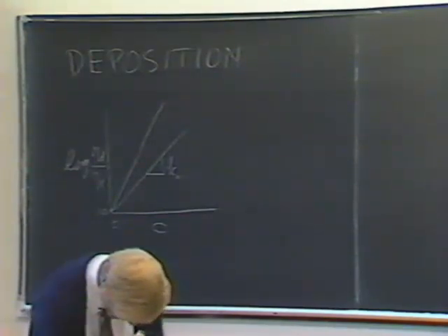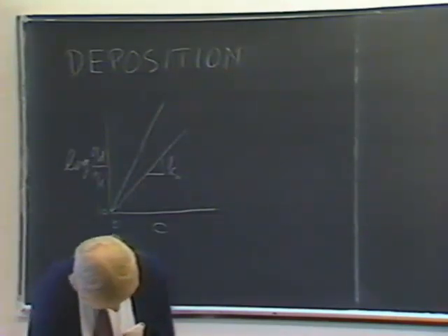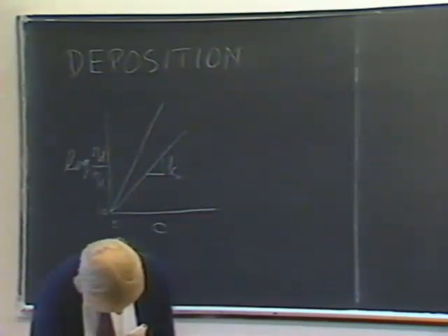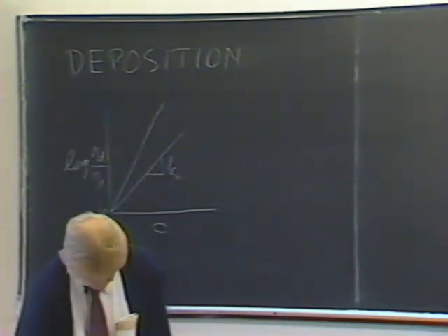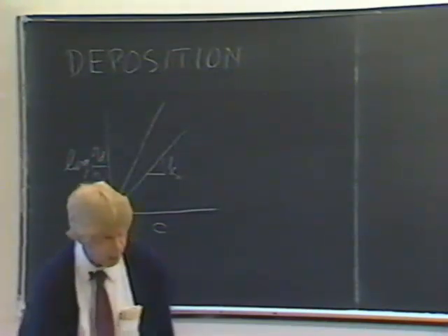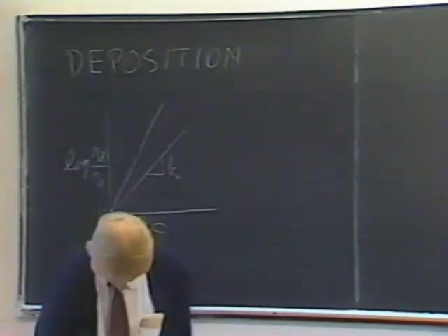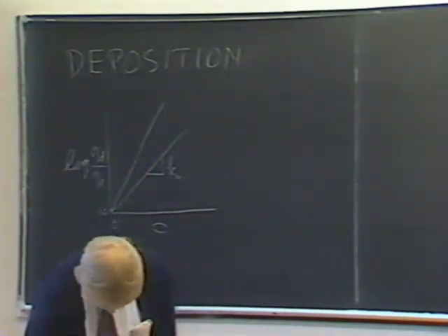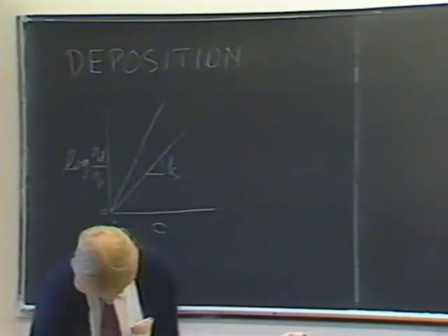The material was weakest at that point, and the knee occurred at about 2 centimeters above the bottom. Very thin layer. 2 centimeters, a little bit less than an inch. Then at 24 hours, the next curve, and you can see that the knee is a little bit higher, and that the curves are both higher, and so on. If you look at the rest, until finally up above the knee disappears.